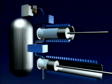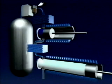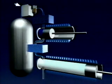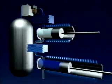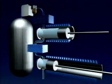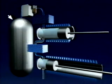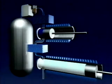From the aftercooler, the air goes to a moisture separator. This separates the liquid from the air and then ejects liquid from the system. An air dryer removes additional moisture so that condensed water or oil does not form in airlines or tools. In a final step, the air goes to an air receiver. The air receiver eliminates pulsations, cools the air further, and then stores it for a steady source of compressed air.